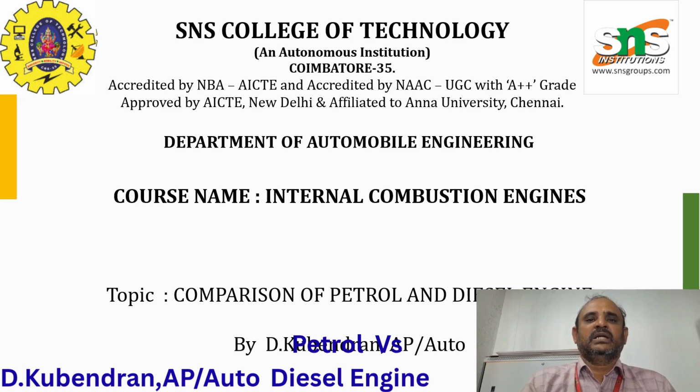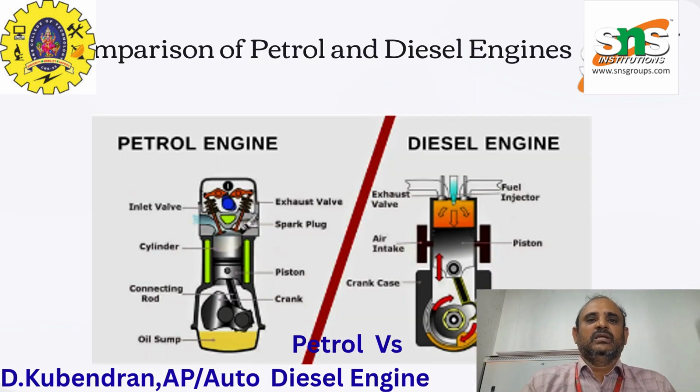The second parameter is ignition type. In what way are we giving ignition to these two engines? In a petrol engine, spark ignition is provided using a spark plug. In a diesel engine there is no spark plug; instead there is compression ignition, because the diesel engine has a higher compression ratio. The fuel automatically ignites, so no spark plug is required.